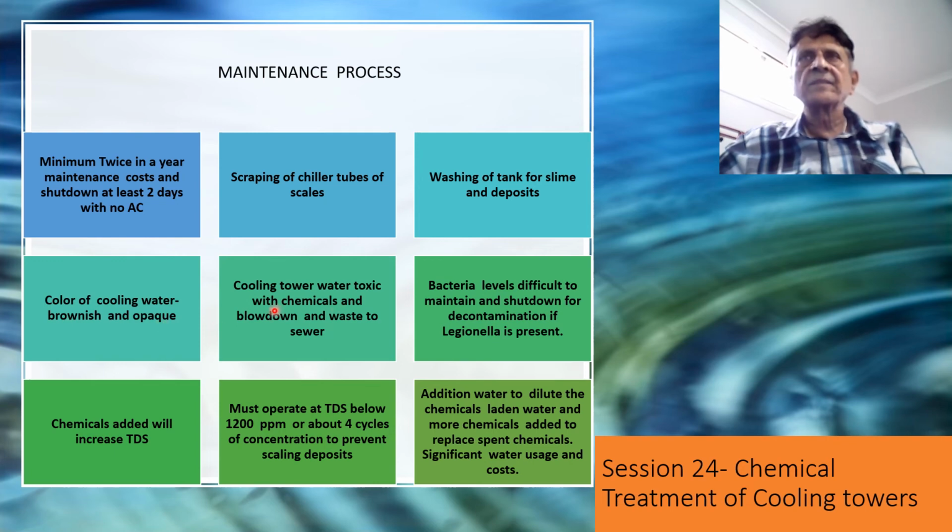The cooling tower, during the maintenance, we have to change it to fresh water. So there's a lot of water loss. The cooling tower water is toxic with chemicals, and blowdown is wasted to the sewer.